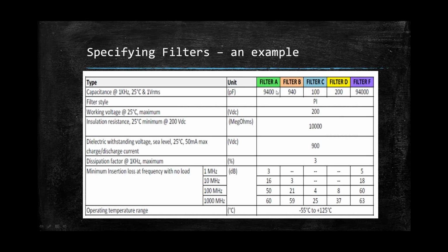Again, you have to look at the attenuation that you require for that connector. I remember working on one design, and they had a very high capacitance on this connector. What happened was that the customer realized that there were 2 pins that needed a signal to go through were getting filtered out. I guess it was a very low frequency filter, and because the capacitance was so high, the connector filtered out that noise.